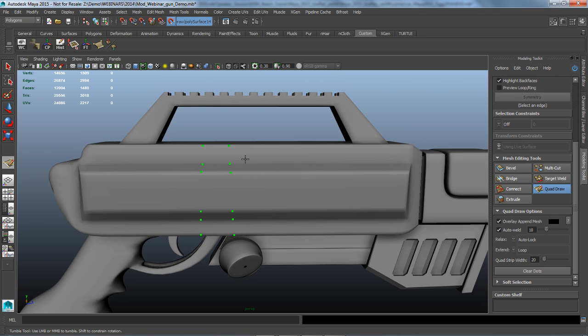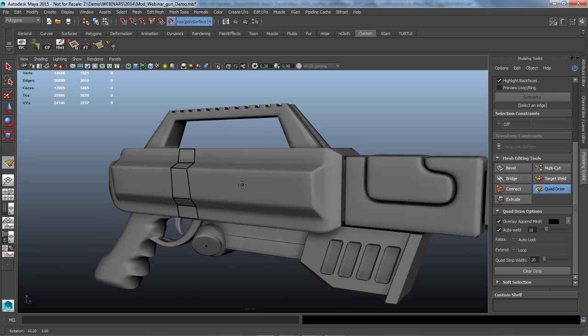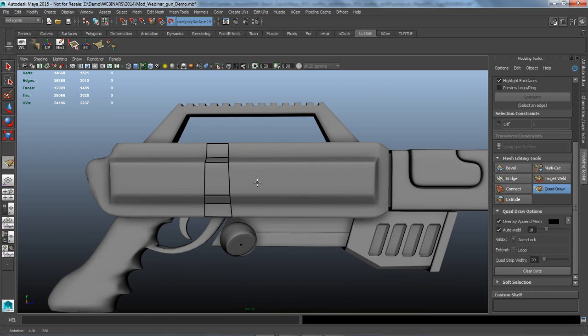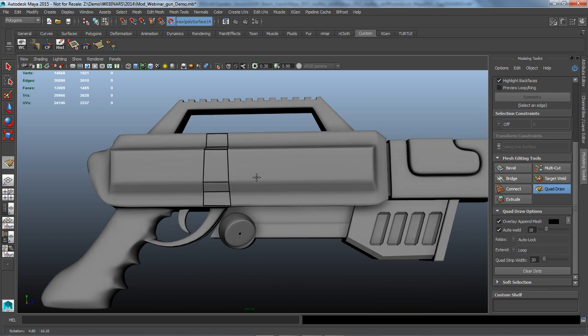Now I've drawn in the dots. Well, what does that give me? If I hold down Shift over these dots, I'm going to get a pre-selection highlighting, or a pre-highlighting, as to the polygon that I'm generating here. So if I click that, I've now generated simple geometry in context to my model underneath. That's a really nice way to work.